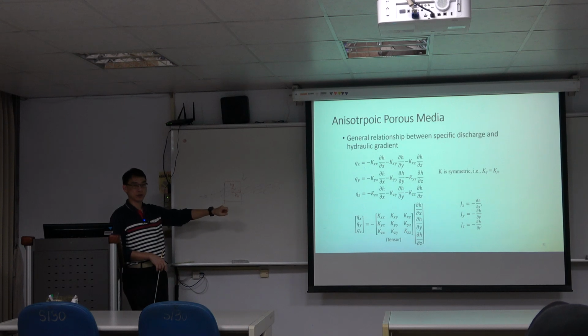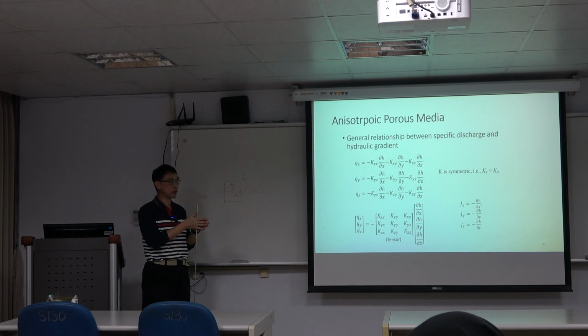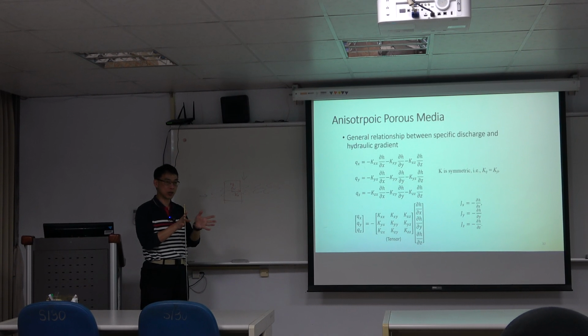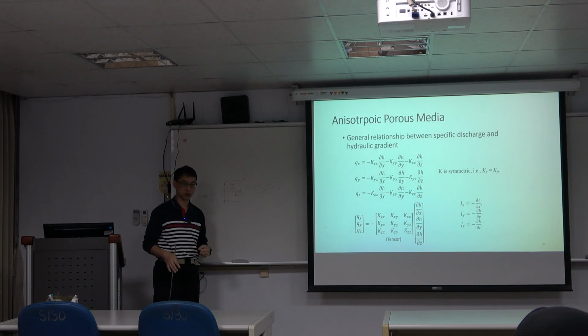Because the fracture system has preferential flow paths, or fracture orientations, they might have two or three sets of orientations for the joints or the planes. So they will be able to assess that kind of geometry, and we can use it in equations to do the calculations. From the geometry of the fractures or joints, we can calculate these K tensors. And then we are able to use this tensor to describe the fracture system in the numerical simulation.